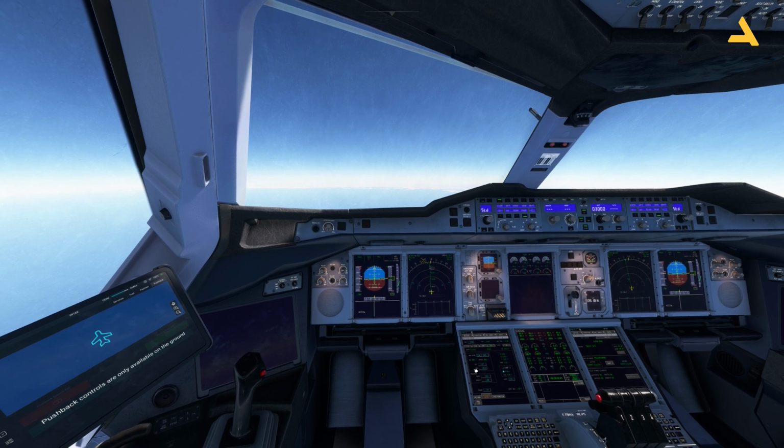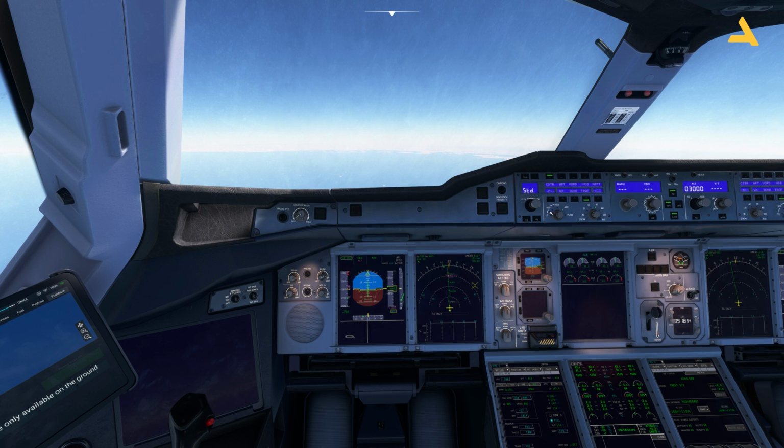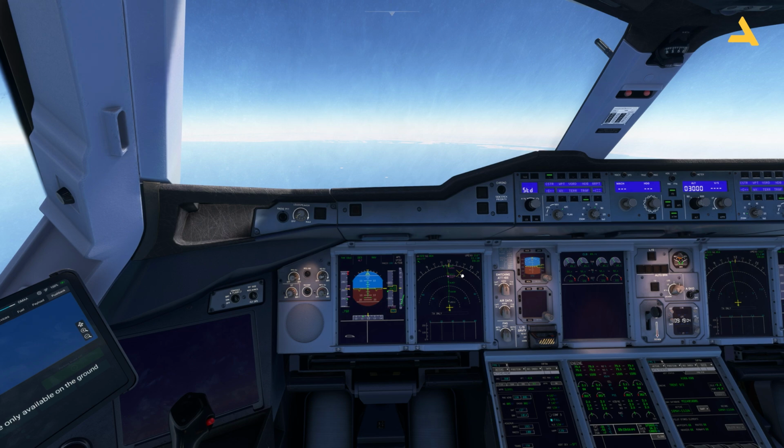So if I'm not wrong, when you activate the approach phase, the plane actually goes to 180 as soon as you start extending the flaps, and then the speed starts to reduce further. So that's how it's done. Thrust is in the idle position. Another thing, this plane really follows all the speed and altitude constraints if you start the descent at a good point, or at the given point.